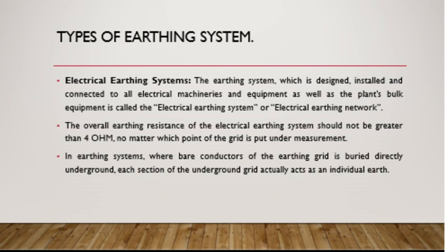But the important point to discuss is that the overall earthing resistance cannot be greater than 4 ohm, no matter which point of the grid is put under measurement. And what type of conductors will we be using? We'll be using the bare conductor, which is very highly conductive in nature, and it will be dug inside the ground, and it will simply be treated as an individual earth.